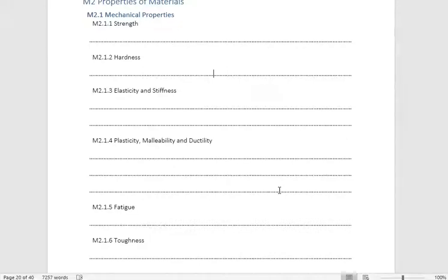Okay, fatigue is the tendency to fail under cyclic load. The idea is that things like planes, which are under repeated, even very small amounts of load, way less than what it needs to fail, can eventually fail because it's so persistent and repeated in a cyclic manner. The analogy I use here is that you might be able to bench press, I don't know, 80 or 200 kilos, whatever it is.